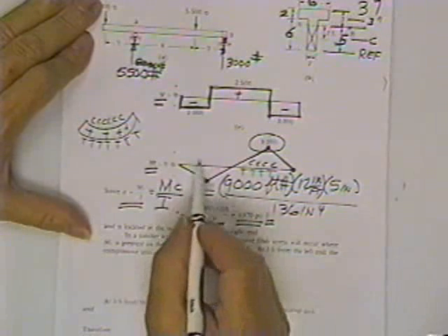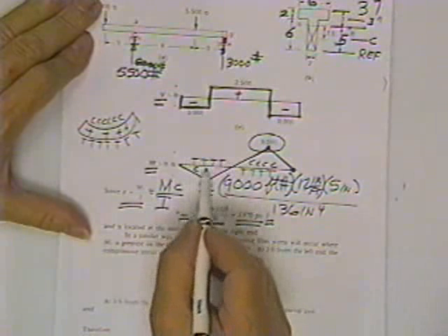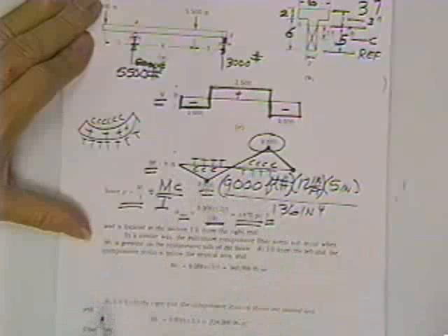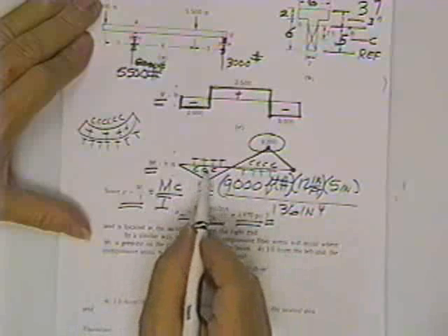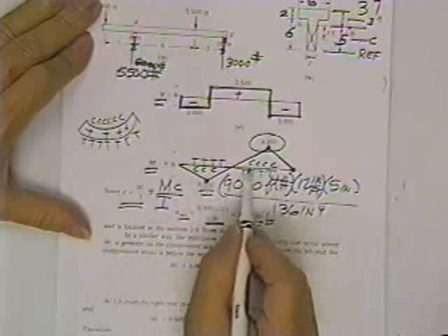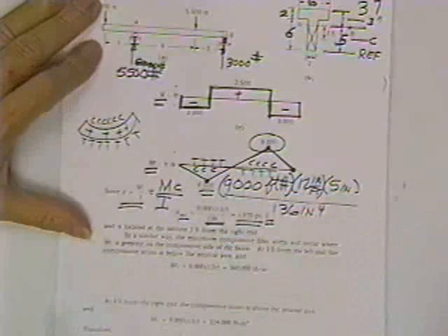All right, in this region, there's tension on the outside. There's always compression between the line and the moment diagram. So you can just put little C's inside, put little compressions inside between the zero line and the moment diagram.